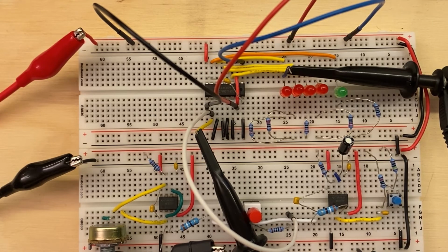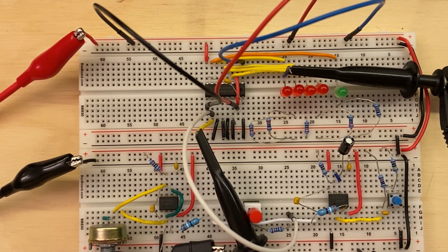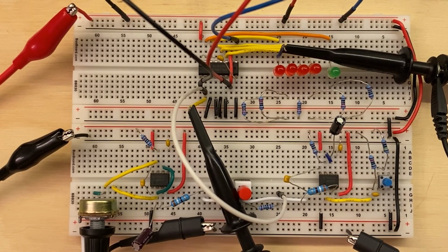And sometimes you'll see that happen to your clock signal, and you'll be wondering, hey, what's happening? Why is my counter, and it's not just counters, it's basically any chip that takes a clock signal and works on that positive edge. Any one of those chips, that situation can happen if, for whatever reason, there's too much parasitic capacitance, and your clock signal is not rising up fast enough. You could get that metastable state and that erratic behavior from your chip. And so as we go on and build our circuits, it's something to look out for whenever stuff goes wrong. You always got to make sure that the clock signal is correct and sharp.